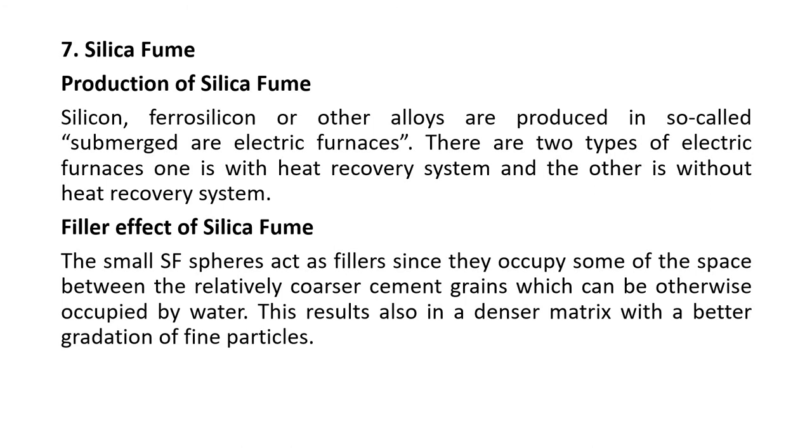Filler effect of silica fume. The small silica fume spheres act as fillers since they occupy some of the space between the relatively coarser cement grains which can otherwise be occupied by water. This also results in a denser matrix with a better gradation of fine particles.